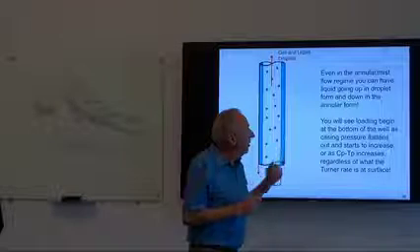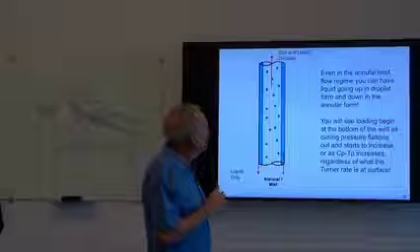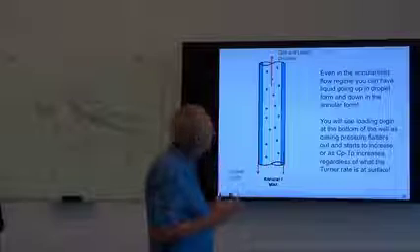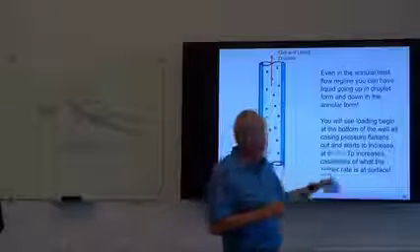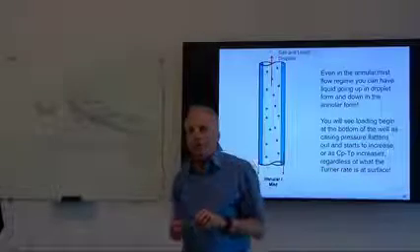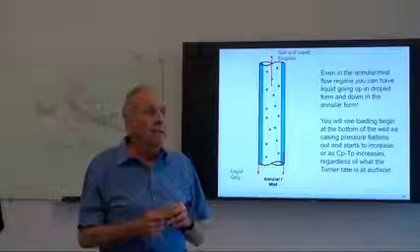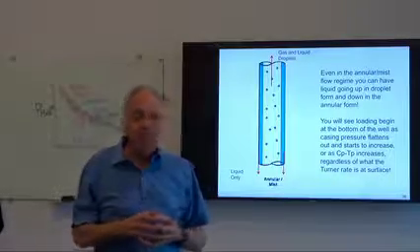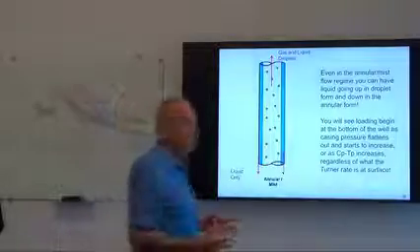So in a free-flowing state, we might see this as the casing pressure flattens out, starts to increase. It means that liquid is dropping down. Or as casing tubing differential increases, that is actually an indicator of liquid holdup in the tubing string, even under free-flowing conditions.